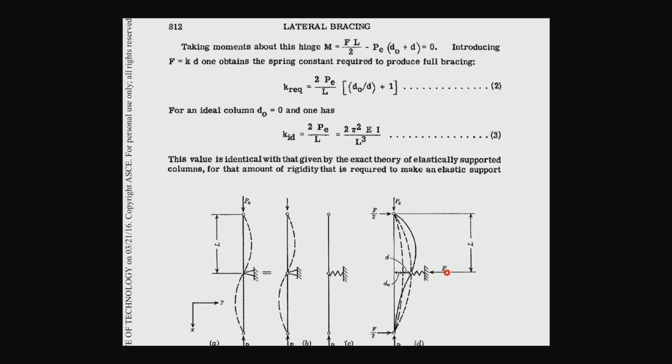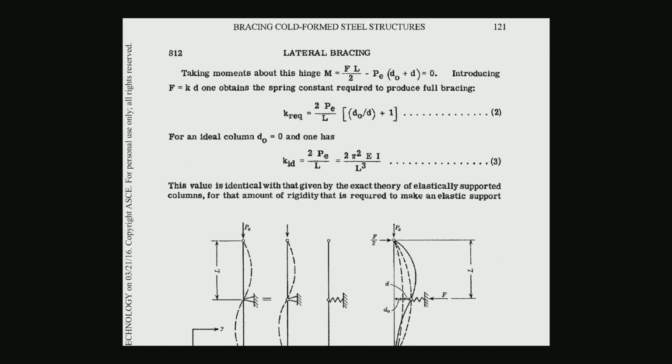But then as the lateral force is exerting back in order to stabilize the column, you can determine the magnitude of the horizontal force at the top and the bottom supports to be F over 2. So you can take the equilibrium about this point. So FL over 2, this is L, F over 2. So take moment about this point, you get the moment going in this direction.